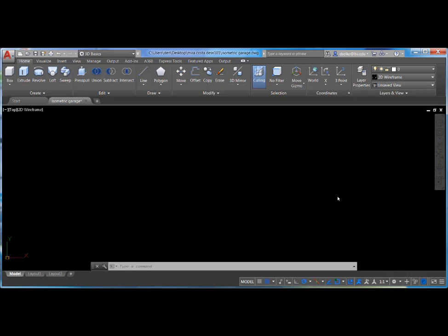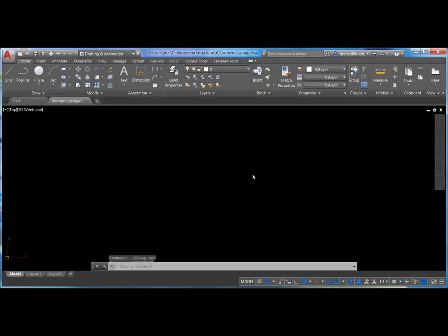To take the isometric into AutoCAD, we will create a new fresh drawing with architectural units. I'm going to go from the 3D Basics workspace and change to Drafting and Annotation. I'm going to make sure that all of my isometric settings are enabled: isometric drafting on, our polar cursor restrictions that force us into 30, 60, 90, and our two-dimensional grid snap with the dots if we wish to display that.